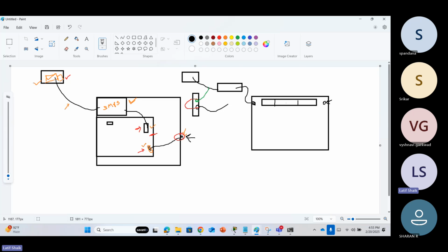So, the charging part. If the charger works, the battery charges. If the battery has power, you can power it on. If the battery is not working but the charger and pin are good, you can still power it on. If the battery and charger are both good but it still does not power on, it means a button issue. The power button may have failed, or the button's connection to your motherboard may have an issue. So you have to change that.